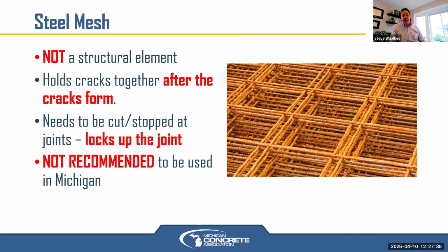But to be used effectively with a good joint spacing to control cracking and not have any cracks, it actually ends up being worthless. Because each layer of wire mesh has to be sized such that it's smaller than the slab that it's in, the joint spacing. So if you have 10-foot by 10-foot squares, your wire mesh should be cut to 9 by 9s or 9.5 by 9.5 foot max pieces of wire mesh embedded strictly within each slab and not going across the joints,